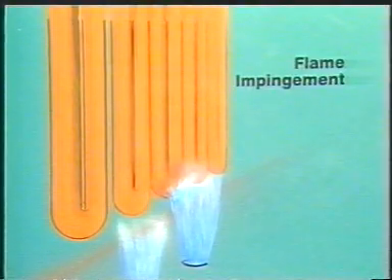The fire should always be kept as uniform in length and size as possible. Let's look at some other undesirable flame patterns and consider the causes. A long, smoky flame is caused by insufficient combustion air or insufficient atomizing steam. The flame may be shortened by increasing primary or secondary air or by increasing atomizing steam.